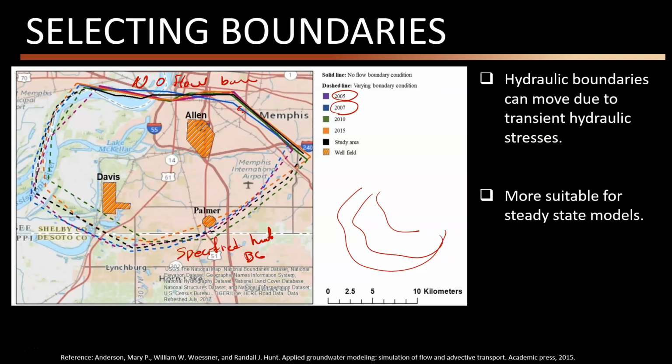So as you see, usually, at least in the small temporal domain, the groundwater boundary conditions are expected not to move significantly. So if you want to model a transient groundwater flow, meaning how the groundwater flows from 2005, for example, to 2015, we can make an average of these boundary conditions, I mean their locations, and define a boundary condition.